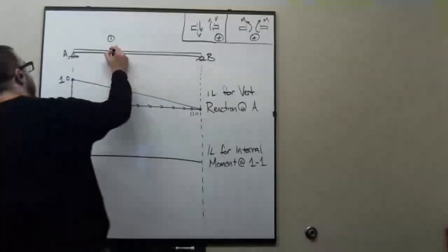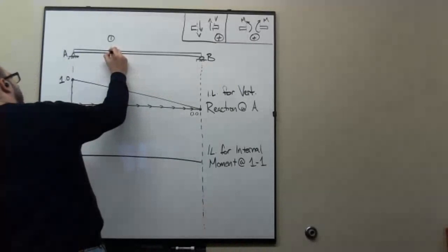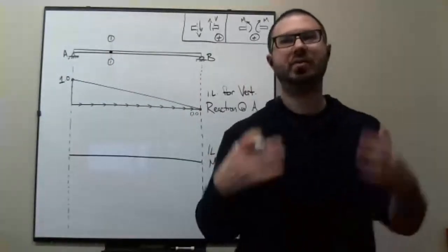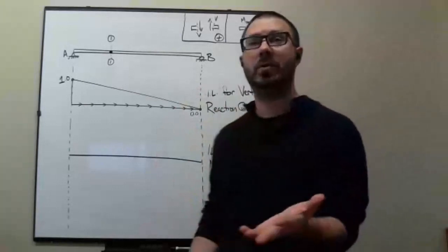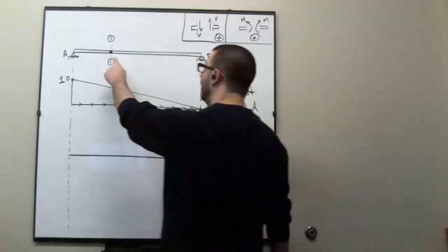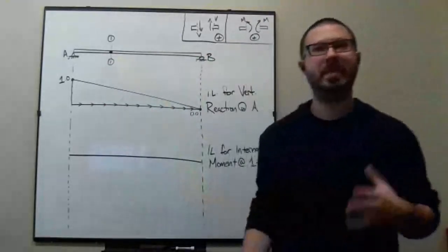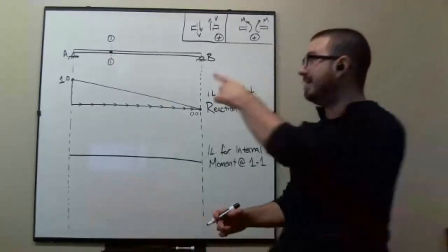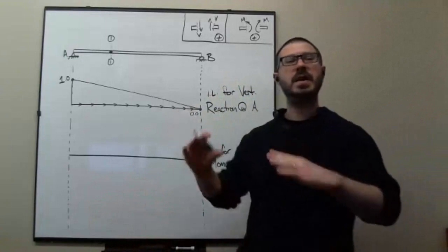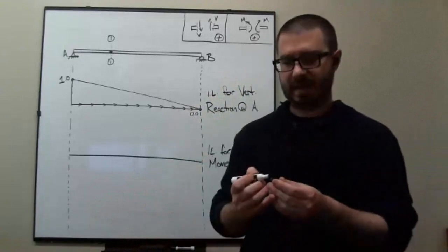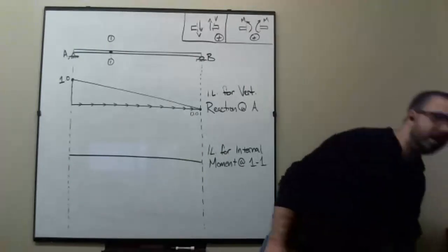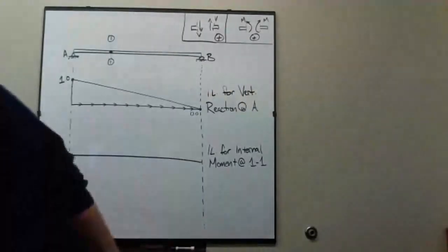So if I put a hinge right here, what is the whole idea of a hinge? Remember, go back to when we were doing support reactions. When you have a hinge inside a beam at a particular point, that tells you that the internal moment at that point is zero. Okay, so think about it like this. Now I have a beam with a hinge, right? I left my fancy little prop at home. I brought it with me in case I had any questions on the homework.